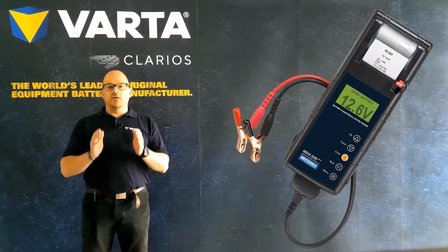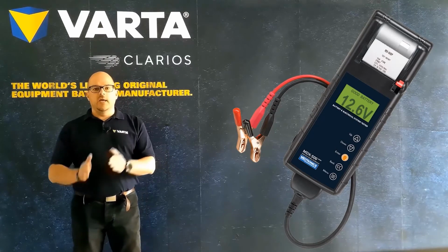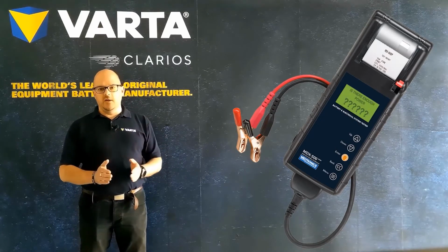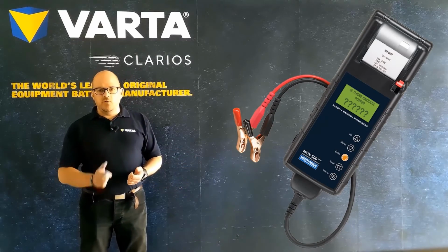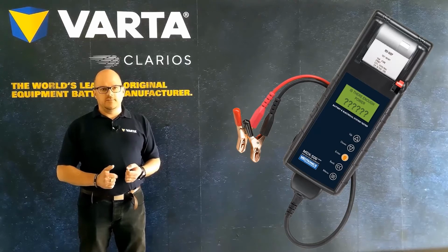A good battery should have at least 12.6 volts, but it doesn't end there. For a battery to be in good condition, you must also know if it is able to perform under heavy load, such as cranking the engine. And again, this can only be identified by testing the battery.